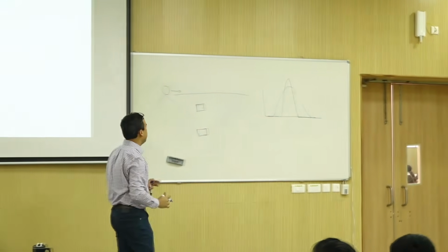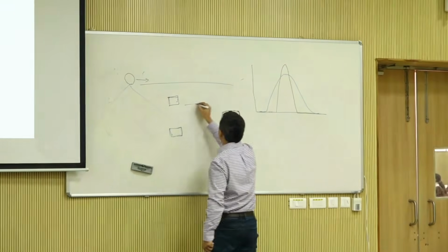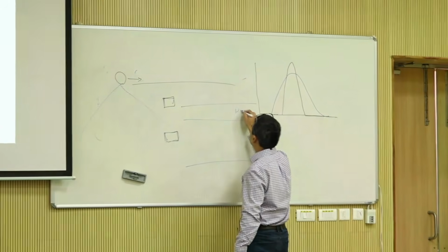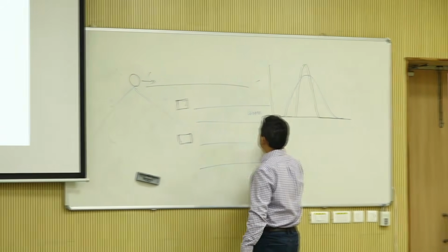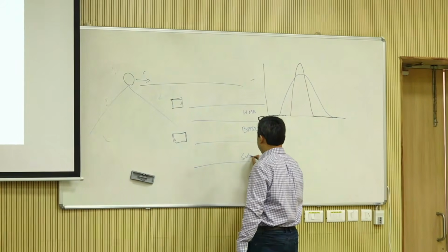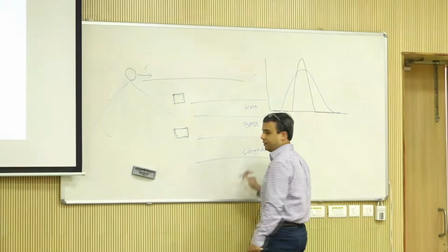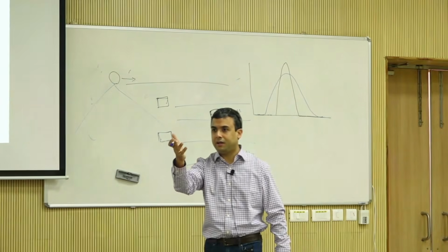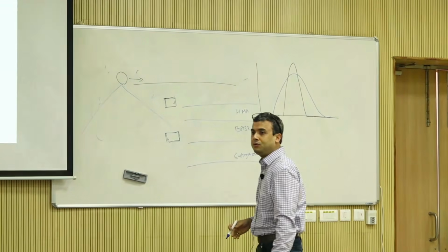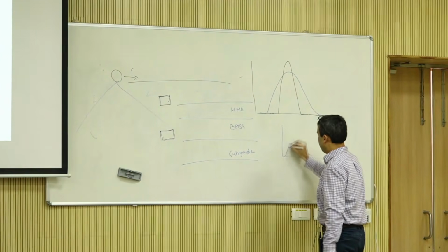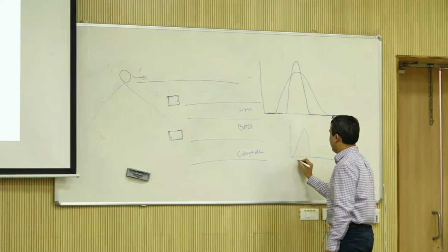Now the question is, you have a layer like this, HMA, base, subgrade. Somebody who knows resilient modulus testing, you have run it, right? What is the rest period you use? What is the pulse and rest period? Do you remember? 0.1, 0.9, right? 0.1 second.